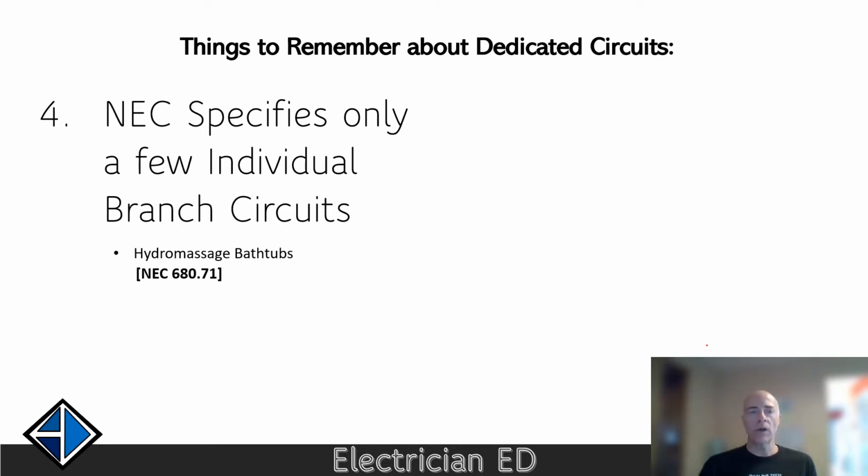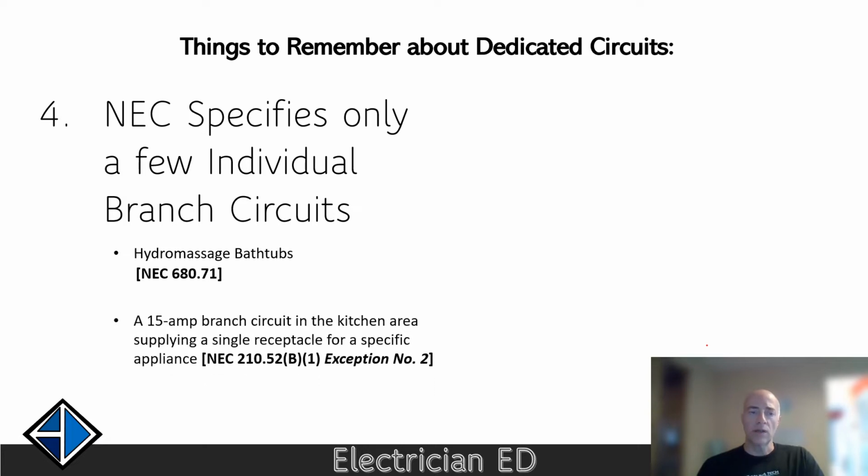You'd have to check with your authority having jurisdiction, your AHJ, home inspector, basically, whether that's appropriate or not. There's other ways to supply ground fault circuit protection for your hydro massage bathtub. In some of the examples I saw, they actually required more than one circuit for all the equipment being used in a hydro massage bathtub.